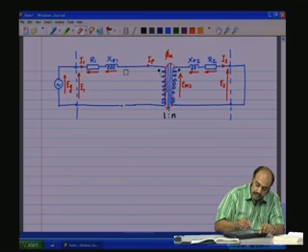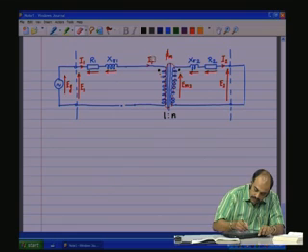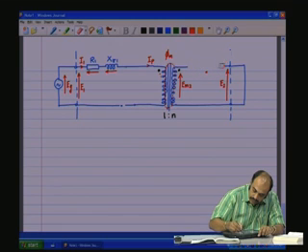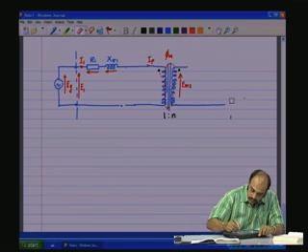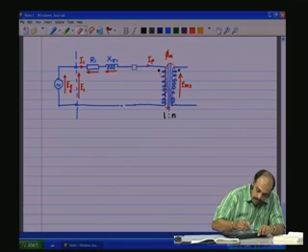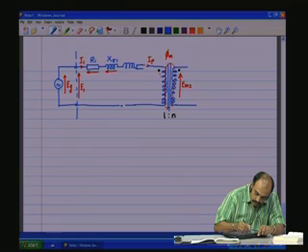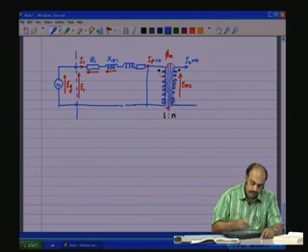And we can do one more thing, as I was saying. These impedances can be transferred onto this side, which means that we remove these and transfer them onto the primary. So, we include them, and then a short here, I0 equal to 0, I2 equal to 0.